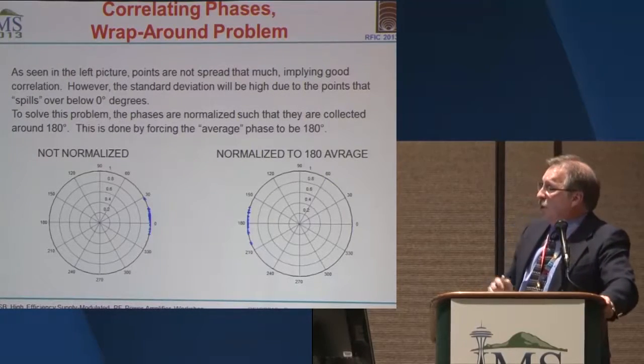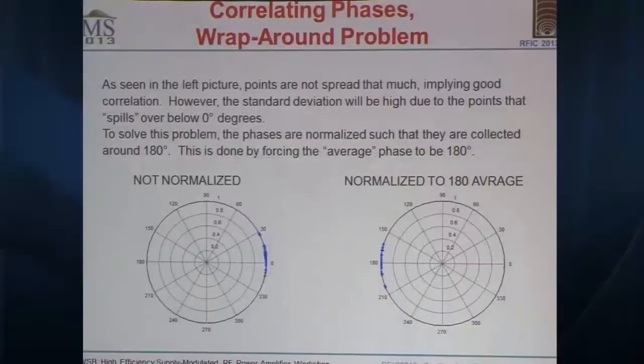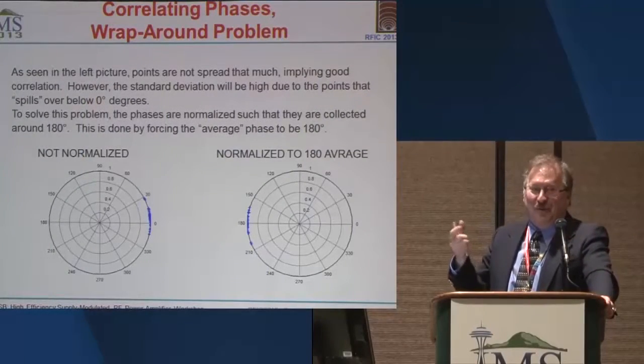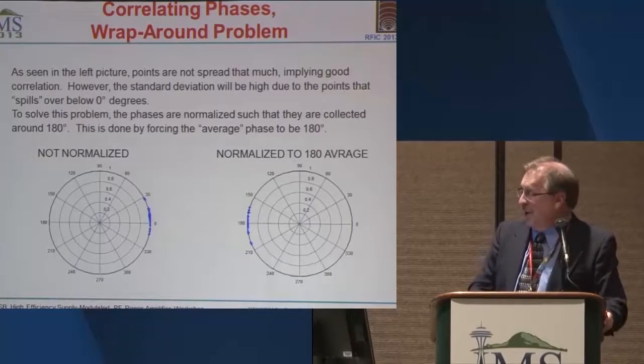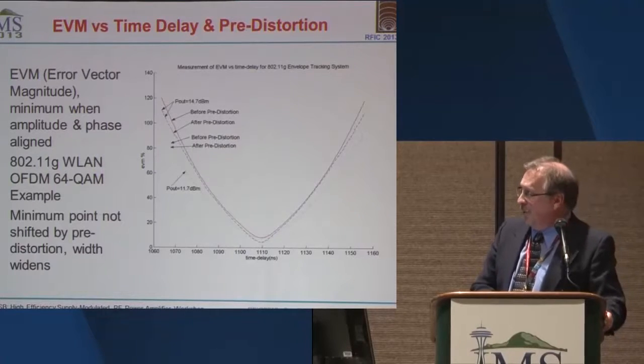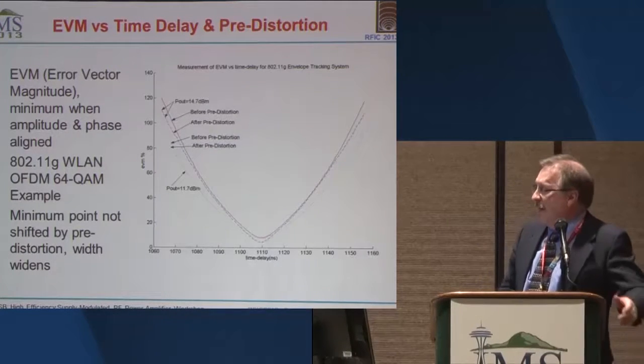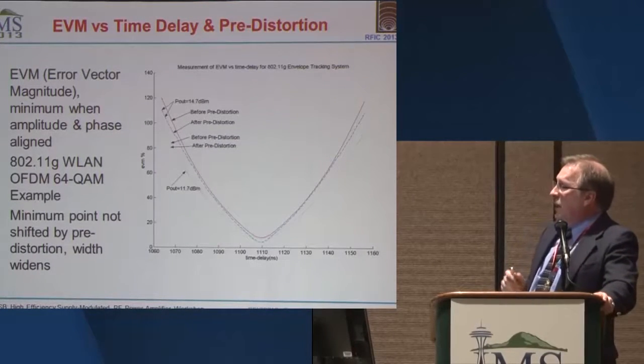And the other thing is where you pick your breakpoint. If you pick it to be around 0, then you keep everybody in one area, especially if you're going minus pi to pi. If you're doing a minus pi to pi and you happen to have your breakpoint around pi, your average will wind up 0, but you really have everybody lumped on either end, and it's not a very good distribution to work with. So there's some challenges with working with the phase cross covariance.